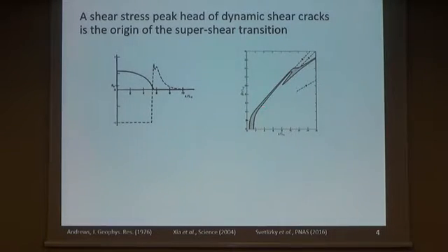You see that the cohesive zone is contracting as it should with linearized fracture mechanics. Then at the same time, this bump ahead is actually propagating, and this bump is propagating at the shear wave speed. You see the slope here. And at some point it reaches a critical load and causes a daughter crack, as it is called, and this daughter crack then allows transition to super shear.